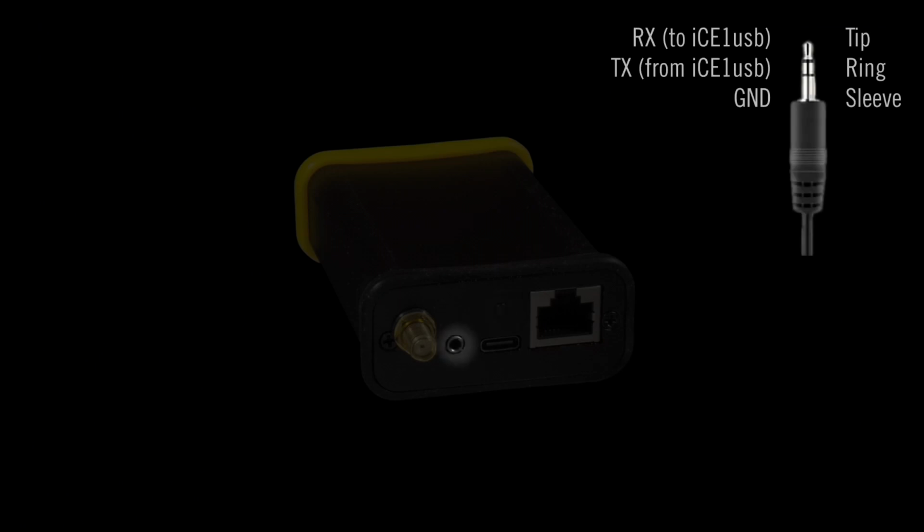Although currently the blinking does start when the host software starts, it doesn't actually stop once the host software disconnects. So yeah, firmware is a work in progress. On the left hand side, there is the 2.5mm TRS jack that's used for classic Osmocom CMOS 3V 3-level UART. This is used for a debug console and should only be needed by developers working on the firmware.